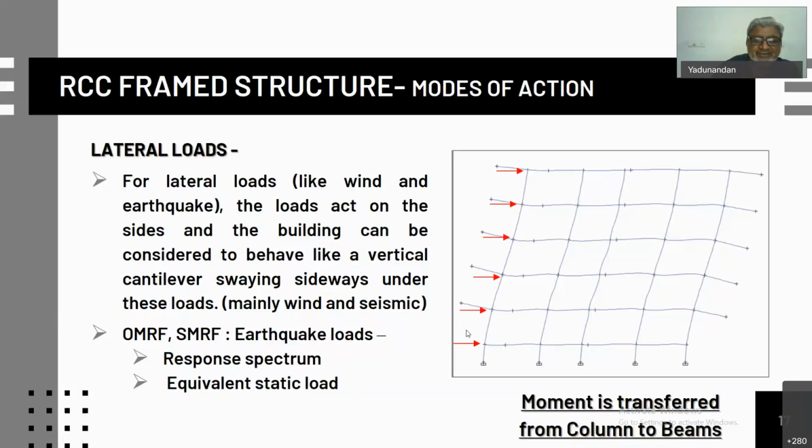But also, depending upon the nature of the region, we consider the intensity or the effect of the earthquake, and we consider the region to be divided into various zones. So you must have obtained this information about the loads and the region, zone 2 to zone 5, and you see how the loads are calculated. For zone 2, we just use what is known as the equivalent static load, and for zones 3 and 4, particularly 4 and 5, the dynamic considerations, response spectrum and dynamic analysis become important.